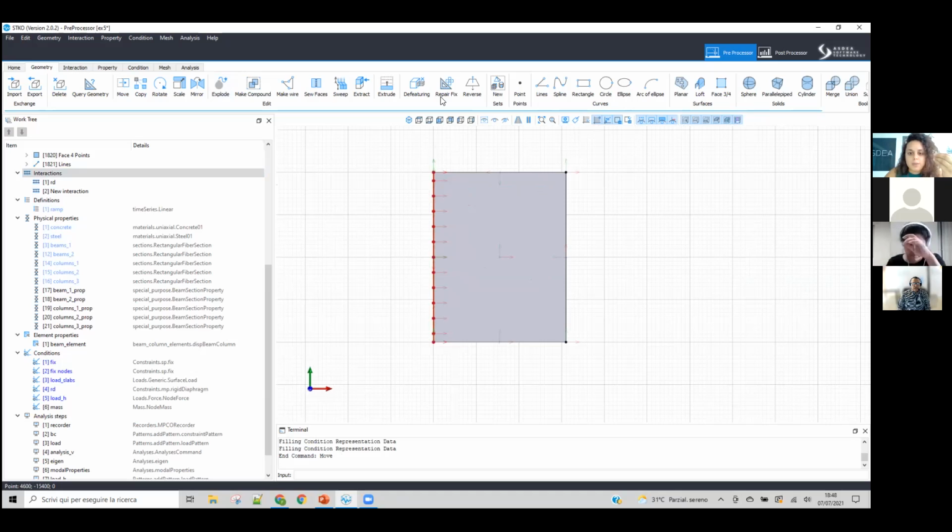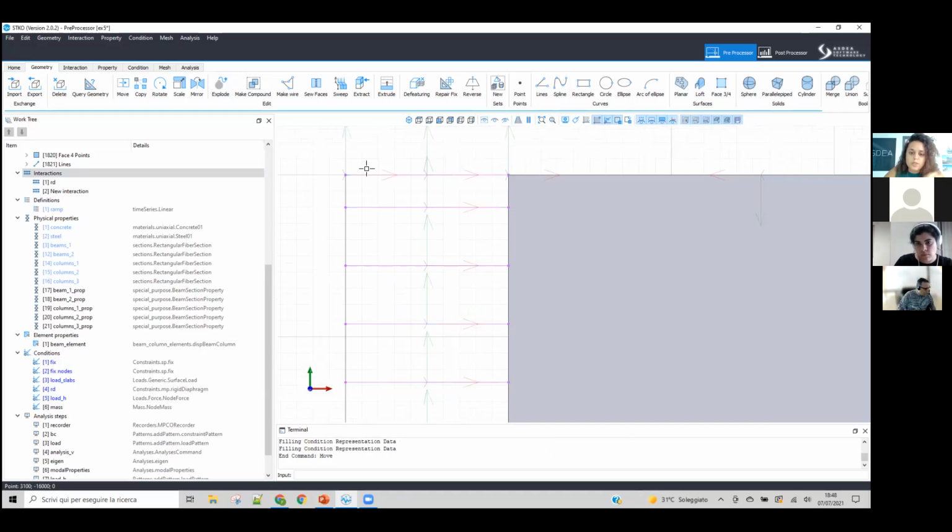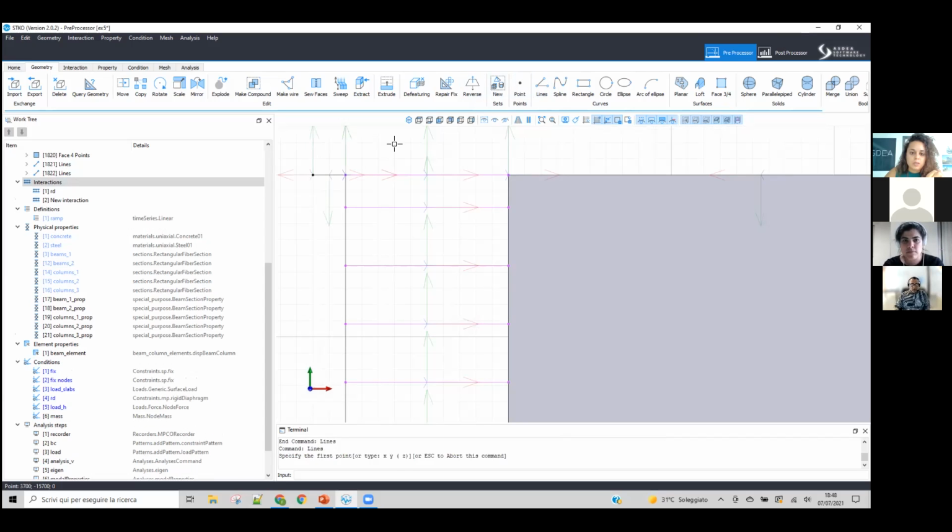What is actually happening with the rigidLink is that you're not just saying that this node moves as this node, but for example, if this one moves and rotates a little bit, I cannot turn my cursor on the screen, but let's say this one does like this, but then also the beam connecting it with the other node is rotating.